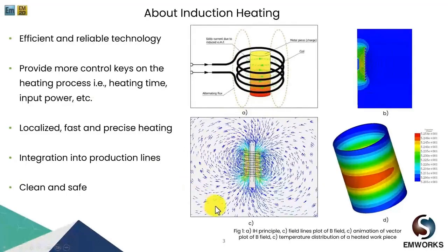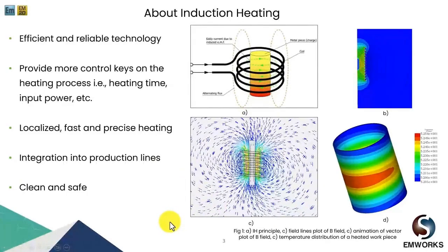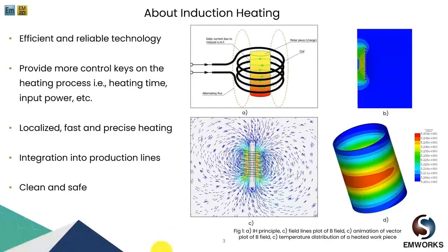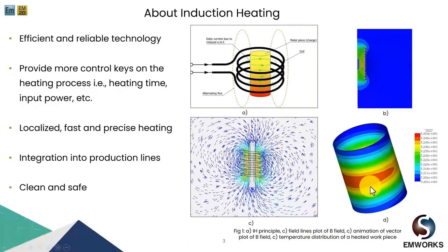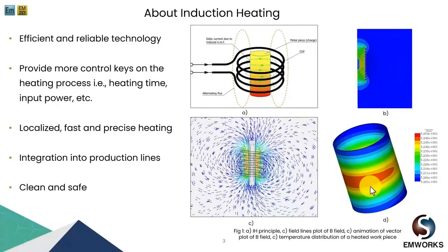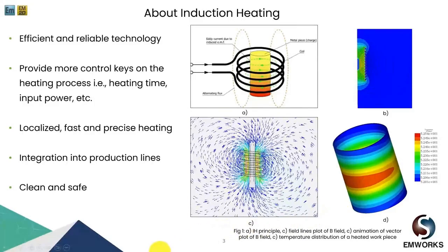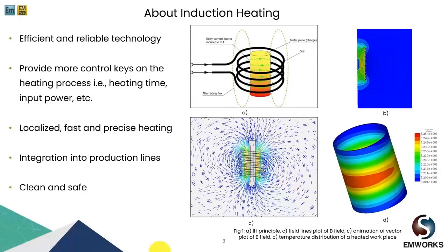When using higher frequency, AC current tends to avoid traveling through the center of the solid conductor, which is called the skin effect. It is then circulating in a thin layer towards the surface of the heated workpiece. In turn, it leads to increased resistance of the conductor, ultimately resulting in a greatly increased surface heat.